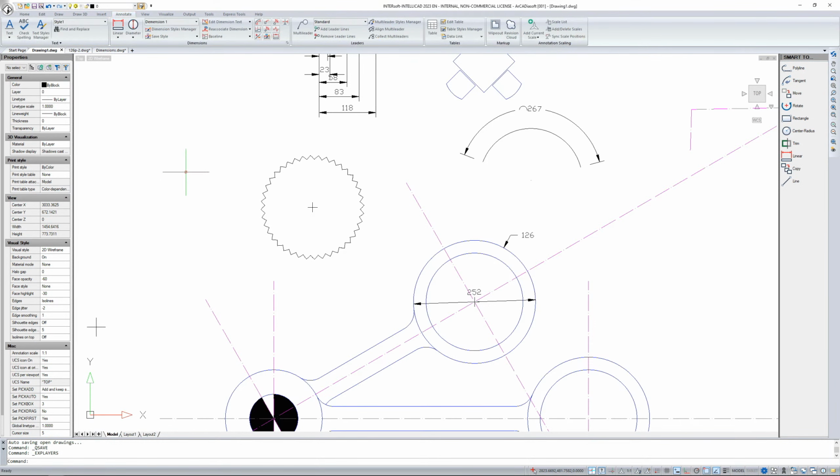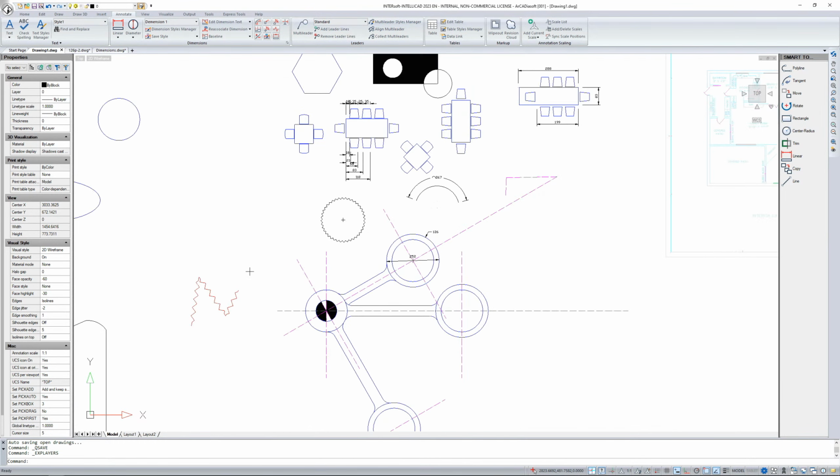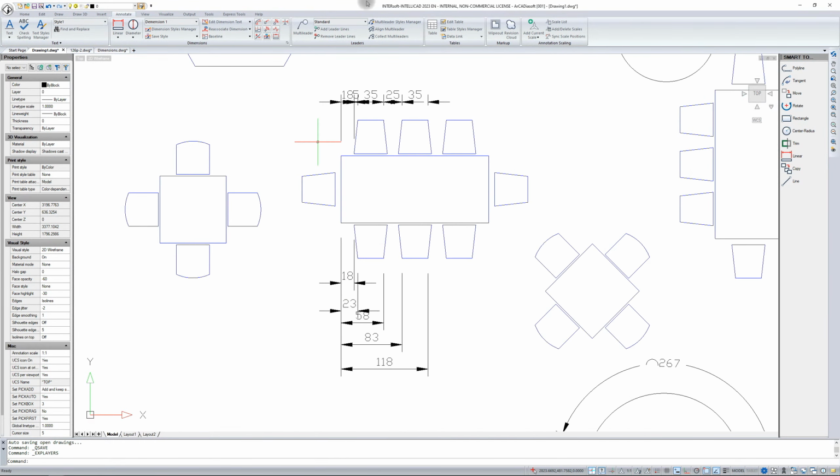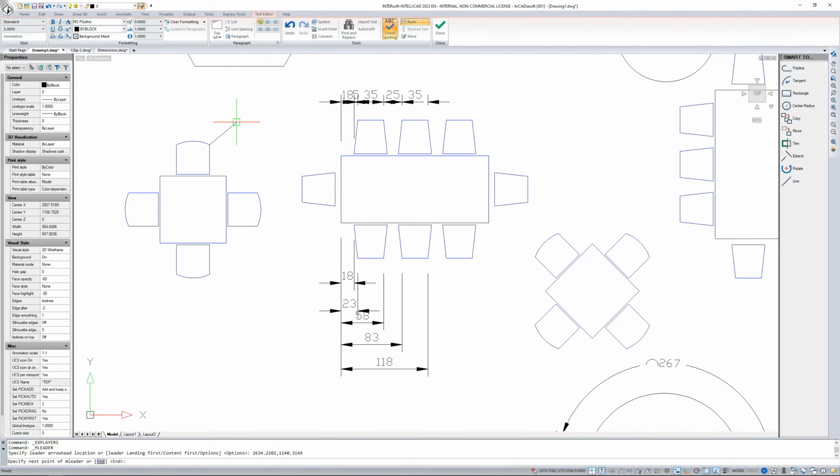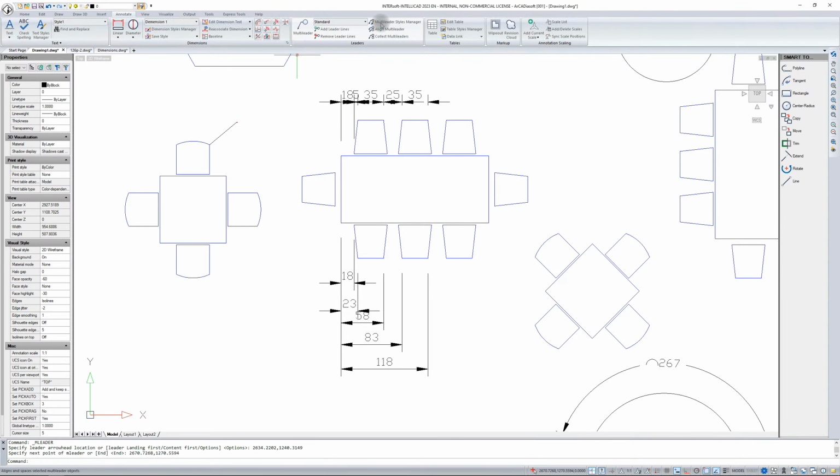When it comes to dimensioning, I would like to discuss one more thing. Maybe it's not exactly dimensioning, but it is possible to introduce a multileader simply to show and describe elements. And here too I suggest that you start by defining this reference line before selecting it, for the simple reason that it will be the same as in the dimension. This default size is so small that you can still see something while typing, but after you enter it, it won't be visible anymore. I choose the multileader style manager.